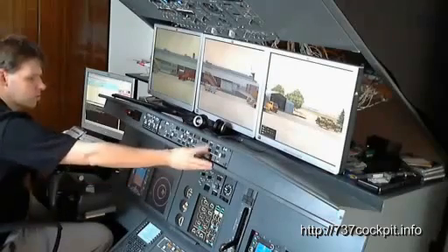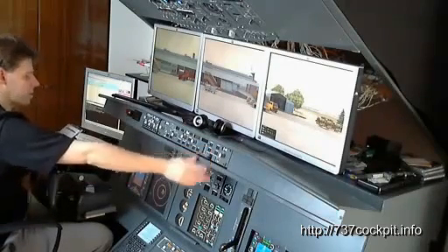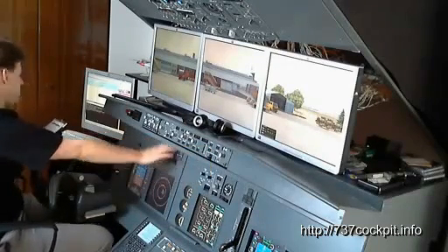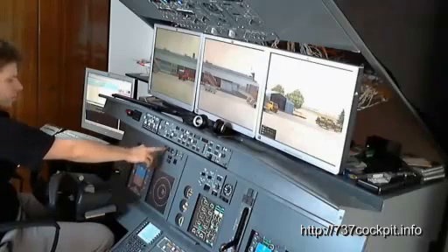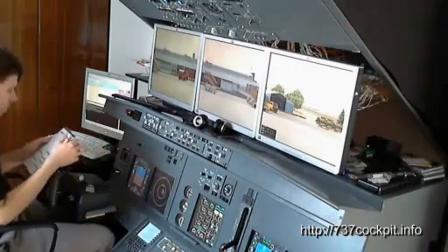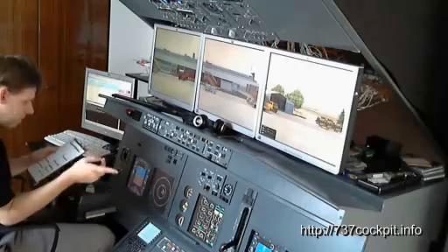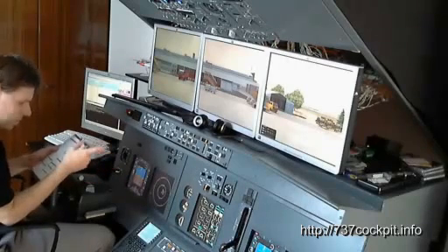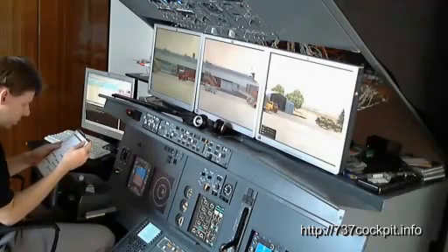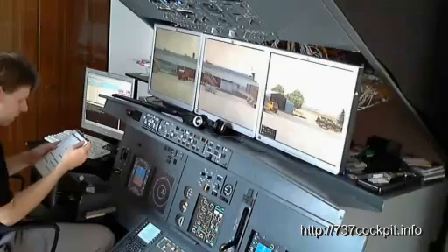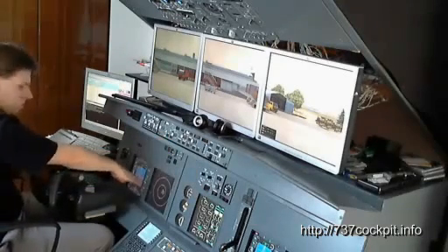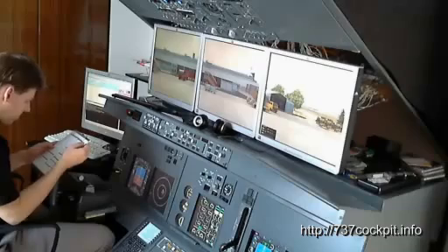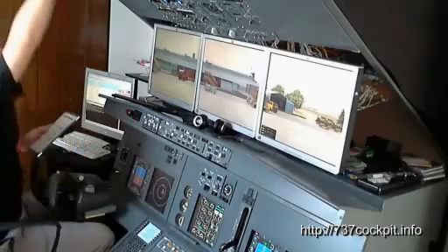Autopilot is disengaged, so we engage and disengage the autopilot, so we can check also in our main instrument panel. We have the indication autopilot press to reset to remove the indication. Landing lever is down and checked, flaps up and no light, spoilers retracted, speed brake off. Flight director is on. We can see now our flight director. Flight controls on.